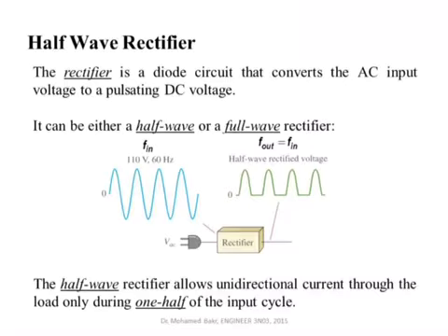All of us use all types of electronic devices, and these devices take the outlet AC voltage and convert it to a DC voltage that we can use to supply our electronic circuits, like tablets, cell phones, and so on. So inside every power supply that converts from AC to DC, you must have a rectification circuit, and the diode is a very important part of this rectification circuit. As I explained, a rectifier is simply some sort of diode circuit that converts an AC voltage into a DC voltage.